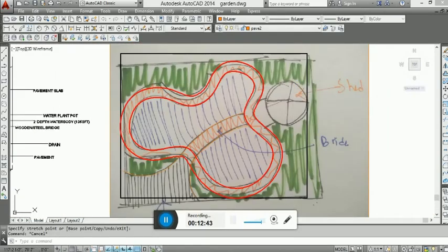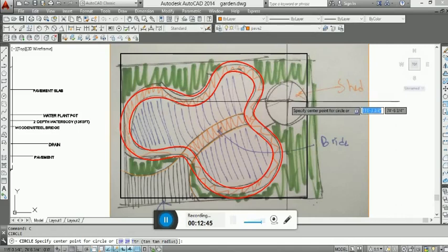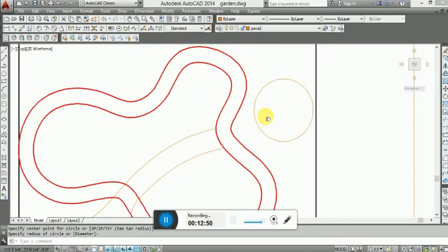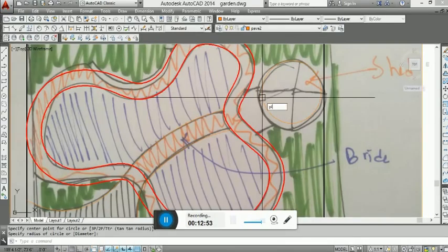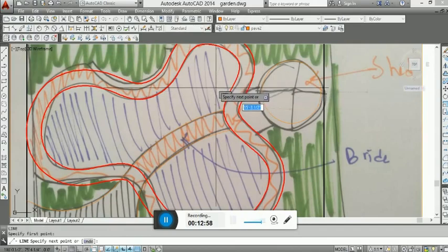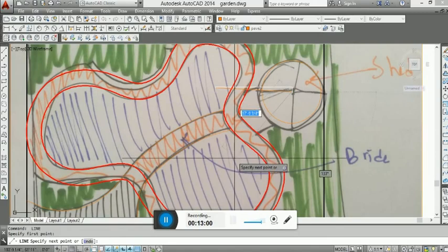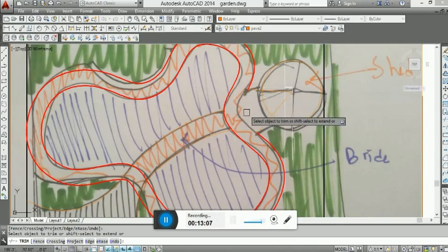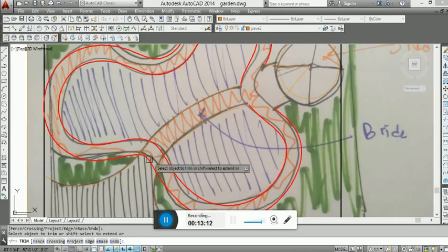Then the remaining part is actually the shade, or maybe the barbecue shade. So I am giving the C space command, and I see from the drawing that it's nearly 5 feet or 6 feet, and I will draw L space, taking the center as my starting point and clicking just randomly, because from the poolside walkway to reach the shade I will have a large space. Now I'm trimming the point I don't want. This is the walkway, so there will be no point in here.